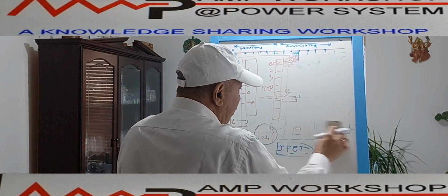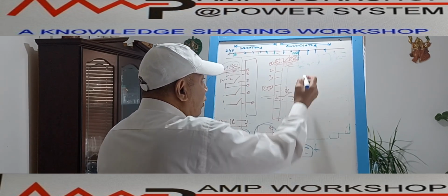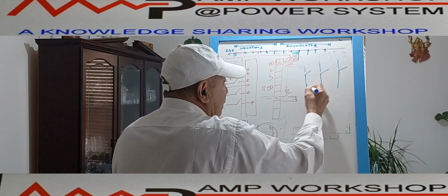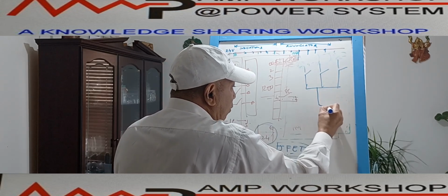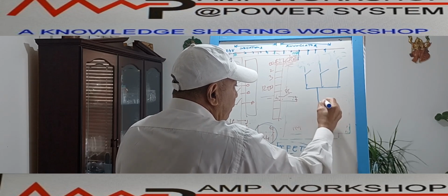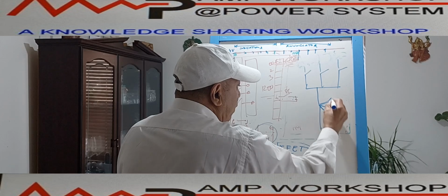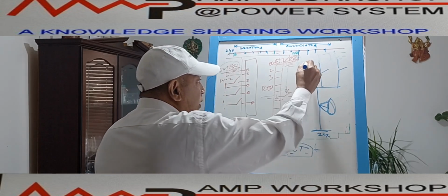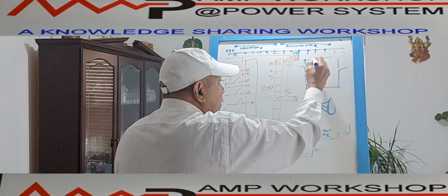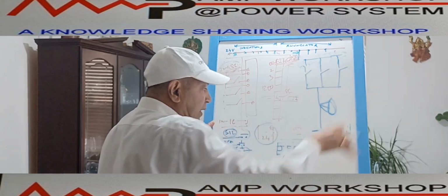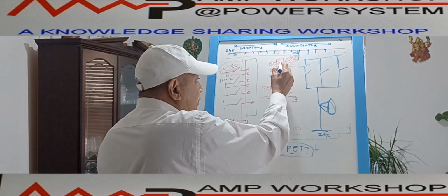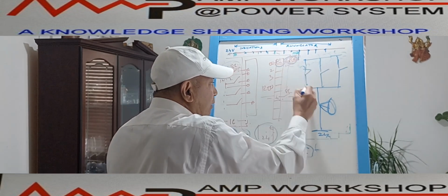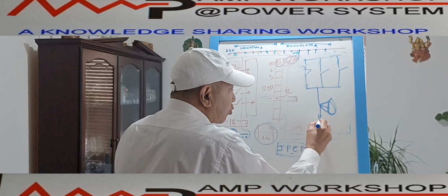Suppose all these relay one NO contacts are connected in parallel, and then go to the horn, and the other side goes to the 24-volt negative. Internally it is distributed and goes to the positive side of the 24-volt DC inside the annunciator. So when any of the output relays operates, the indication lamp comes on immediately and that gives the horn. And here is a silence push button.